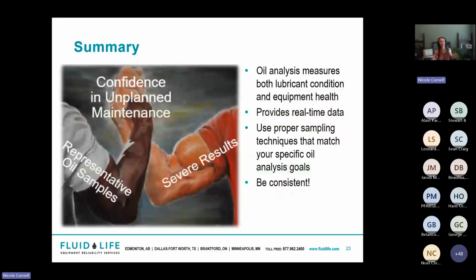So in conclusion, oil analysis is a simple and powerful way to monitor both lubricant condition and equipment health, as long as you use proper sampling techniques. The reason why oil sampling is critical is because it provides real-time data that planners, reliability engineers, fleet managers, and others can use to make decisions. They can schedule downtime, prevent failures, all those things.